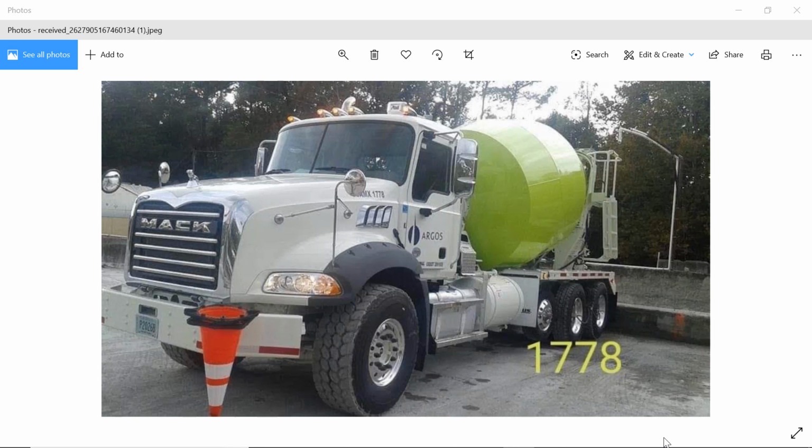2. Free water is equal to free moisture divided by 100 plus 1, which is equal to 1.0403. 3. Adjusted aggregate quantity, 1,620 times 1.0403 is equal to 1,685.286 pounds. 4.